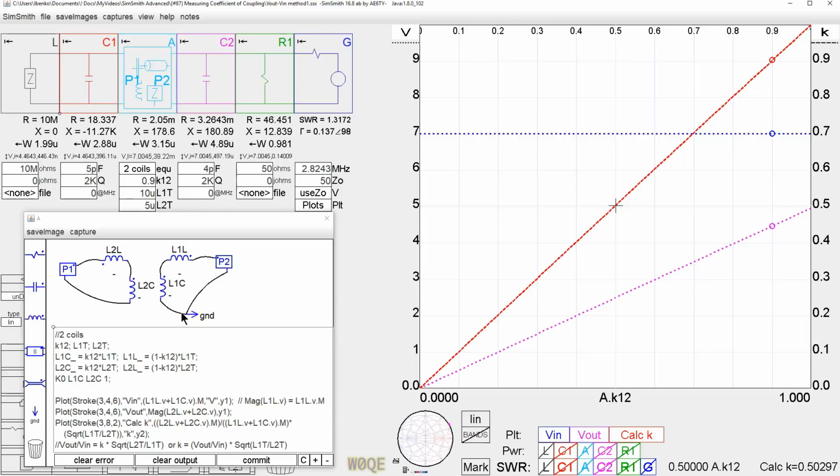What we end up doing is we end up with an auto transformer. Think of this point on the inductor connecting up here, and then we're going to drive this circuit just across one inductor, not across the inductor to ground. But this connection is effectively an auto transformer. You only have 3 terminals. You have one terminal, you have this other terminal, which is common. This is ground now, actually. And then there's the third terminal. You can still make the voltage measurements across it.